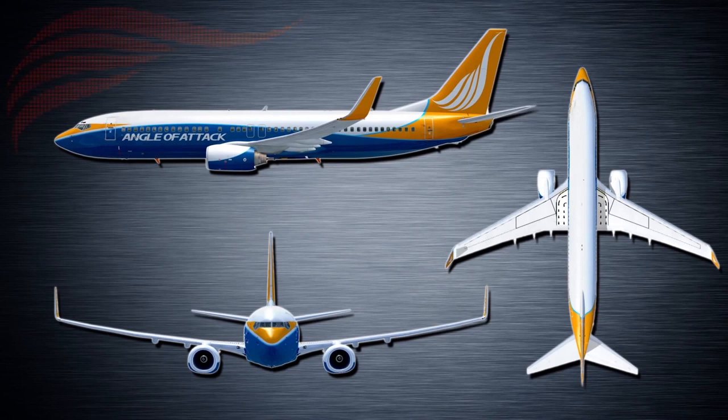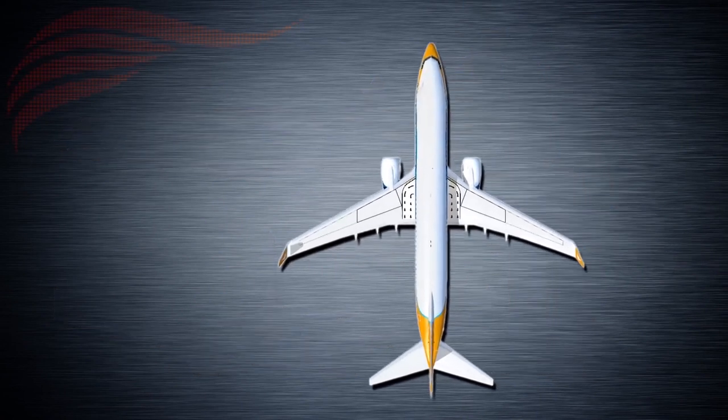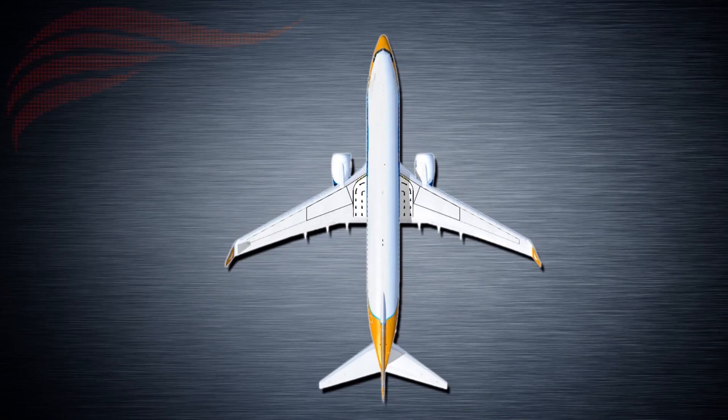There are two groups of flight controls: primary and secondary. Secondary flight controls are covered in the secondary flight controls lesson. The primary flight control surfaces and their direct effects are elevators, change in pitch, ailerons, change in roll, and rudder, change in yaw. An aircraft is free to rotate within the three axes and will always turn about its CG, or center of gravity. The tendency to do this is known as a turning moment.